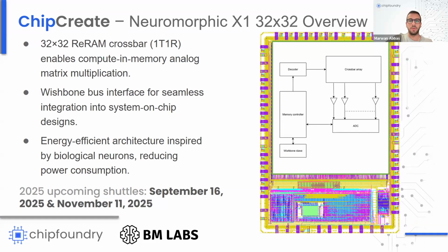Okay, so there's a question about endurance. How many times can you read or write before the ReRAM fails? I think for the endurance data which we will share with you, at least 10K cycles are available for all the working cells in the crossbar array at elevated temperatures, which is a typical number for a ReRAM. If you read the literature survey, it's a typical number for a ReRAM, about 10K cycles.